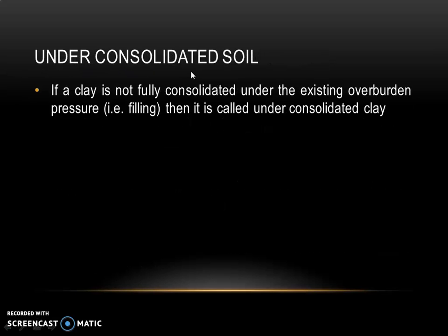Third one is under-consolidated soil. If a clay is not fully consolidated under the existing overburden pressure, that is due to filling of the soil, then it is called under-consolidated soil.